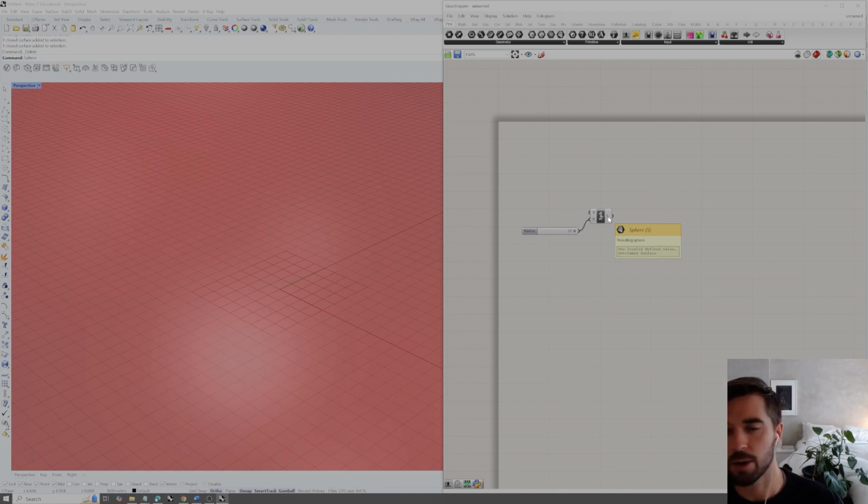If we wanted to see that without just hovering over this information, we can use something called a panel. If we double click in our Grasshopper canvas and type panel, and then hit enter, this is a way that we can both type in information or store information, either text values or numbers, and either pass it into a component as an input parameter, or we can use it to visualize certain output information.